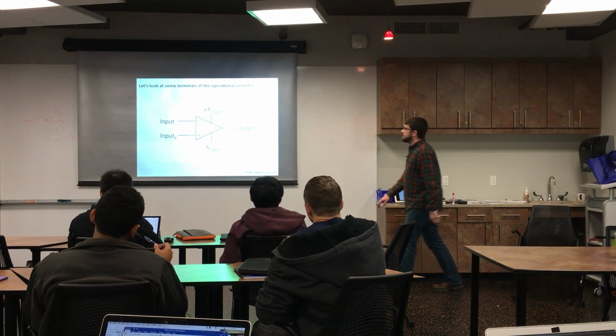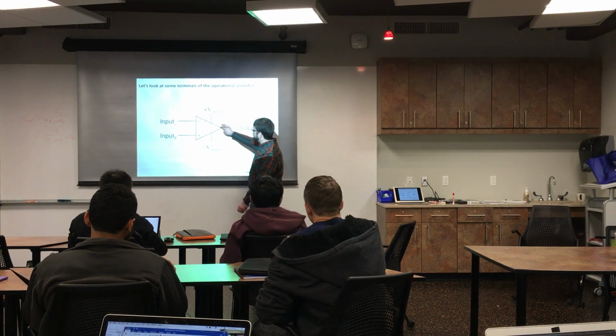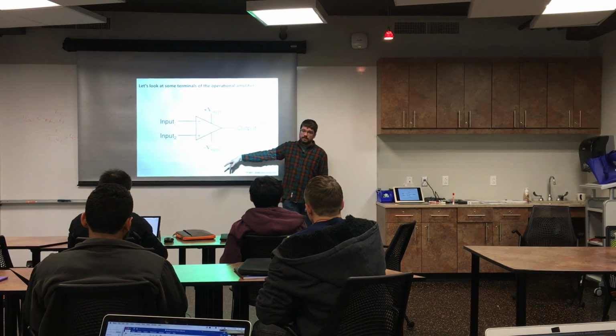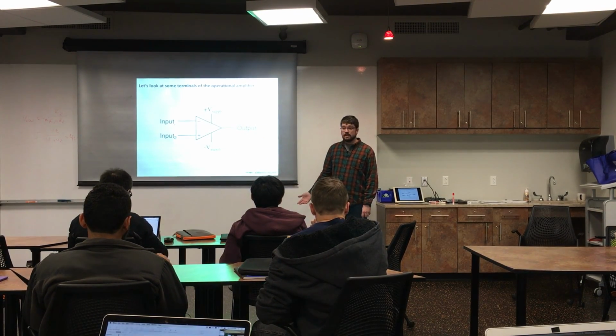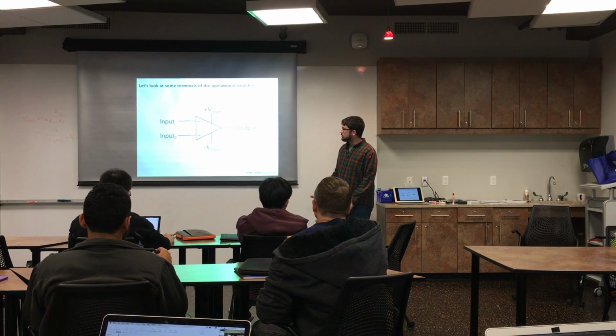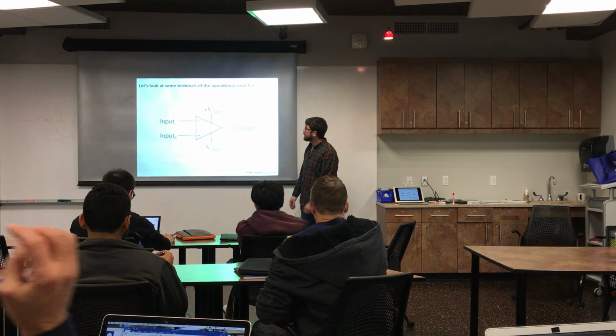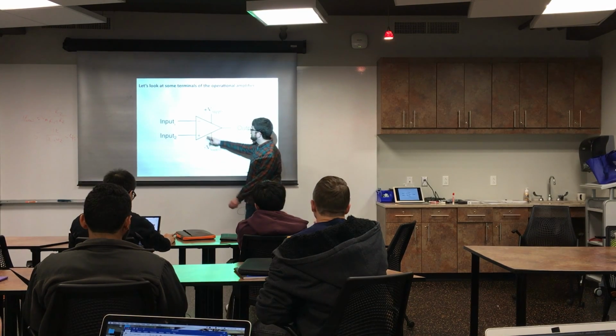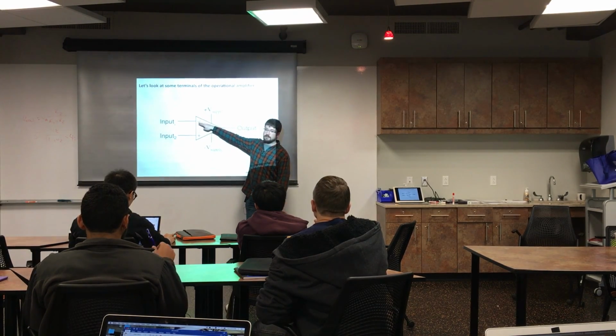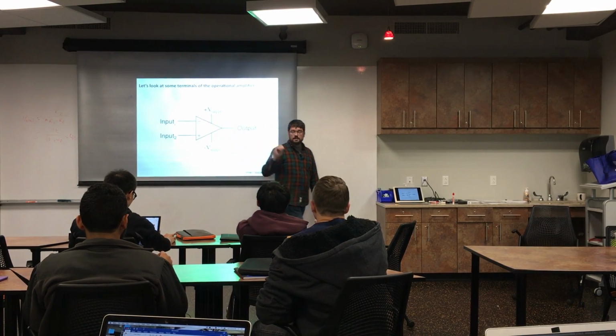Okay, so you remember we talked about these operational amplifiers. This is the symbol for it. They're generally supplied with a bipolar supply, though sometimes you do single-ended supplies, so ground to 9 volts instead of negative 9 to 9 volts, let's say. And they have two inputs, a non-inverting input and an inverting input, and an output.